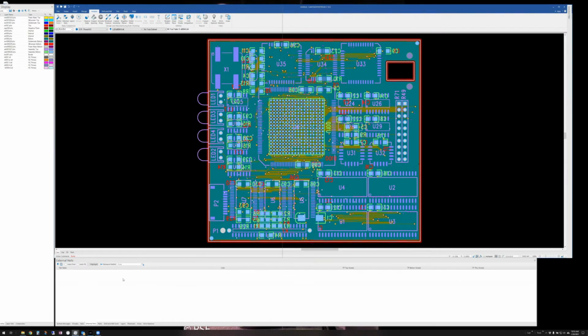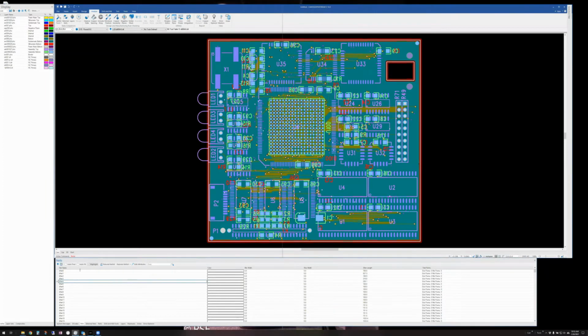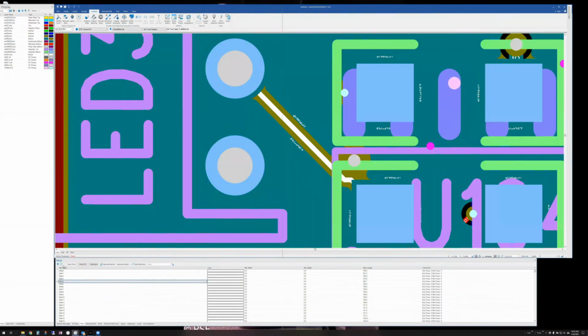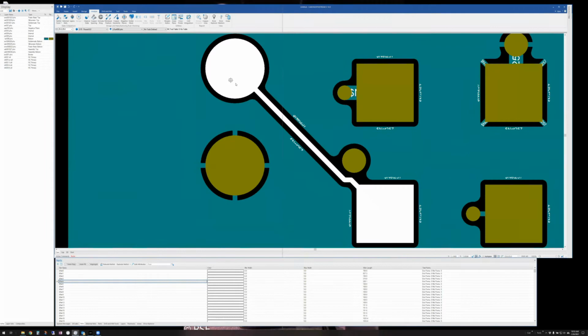So now what it's done, notice there's no external nets here, but I do have Gerber extracted nets, which I can go find and trace, and everything I was just doing, I can go and look at these. But again, they don't have an intelligent net name at this point. But I can go and do that. So if you want to find the closest point net 3 comes to net 5, you can turn them on and off and that sort of thing and look at them.